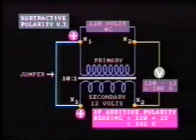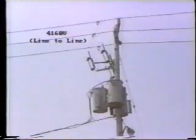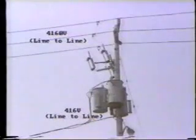Of course, there are other ways of checking polarity, and some equipment that's available also checks ratios. Polarity is extremely important when it comes to connecting up three-phase transformers. Let's consider the case of a distribution transformer, say 4,160 volt primary to 416 volt secondary, connected Y-Y. This could be a three-phase unit or three separate single-phase transformers, as shown here. On a single line diagram, this arrangement would probably be shown like this, with the Y-Y symbols indicating the connections.